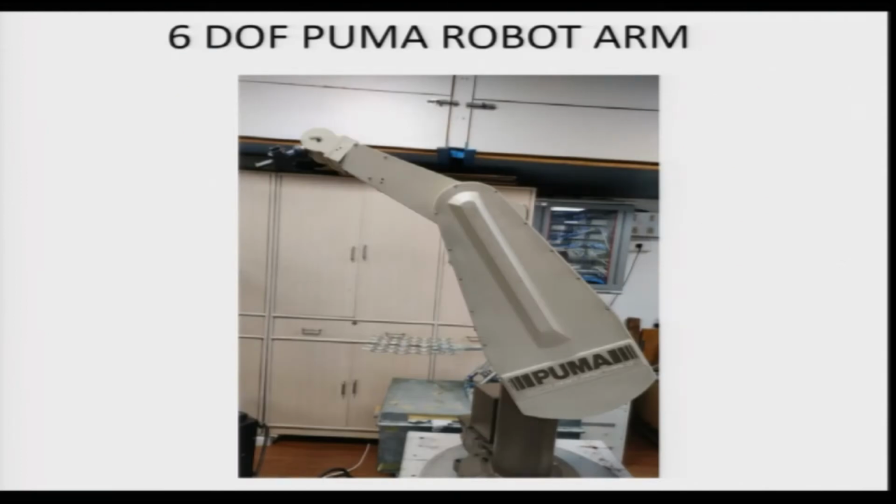So the waist of the robot is an axis, it can rotate about this axis, okay, that is called the waist. Okay. The shoulder axis, so this is a vertical axis similar to our waist axis. So this is going to be my first axis, Z0 and Z1. The second axis is here, which is my Z2. So this can be looked upon as our shoulder axis. The third axis is here, which is my elbow axis, which is Z3.